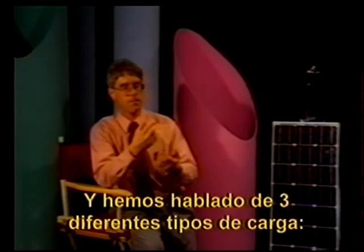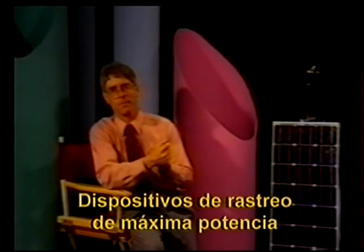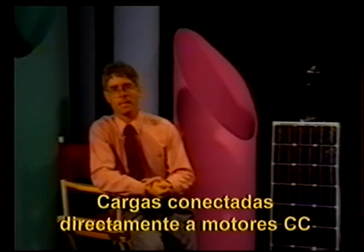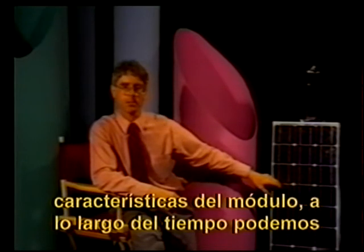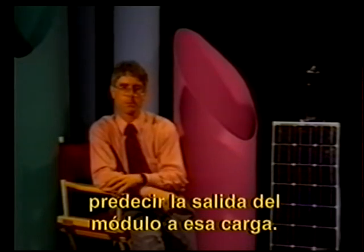And we talked about 3 different types of load classes: maximum power tracking devices, batteries, your most common load, and directly connected DC motors. And we've seen that knowing the characteristics of the load and the characteristics of the module, we can predict over time the output of the module into that load.